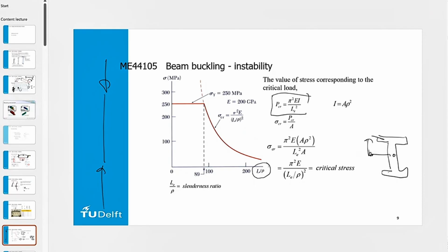Yeah, so, or if you take this formulation, if you assume, okay, we have a buckling limit. That is a load, but we want to calculate with stress. So suppose that there is a fictitious stress at Euler buckling, we assume it doesn't buckle, so we have an imaginary stress. So we have the Euler buckling force divided by the area gives us the actual stress where you can expect Euler buckling.